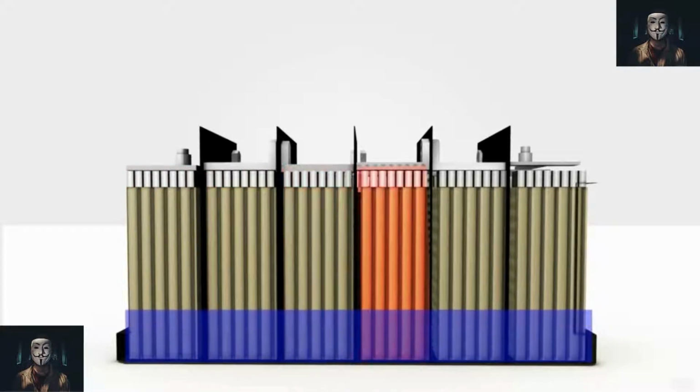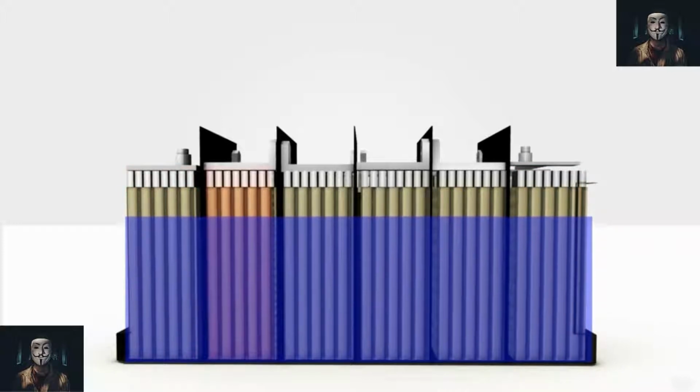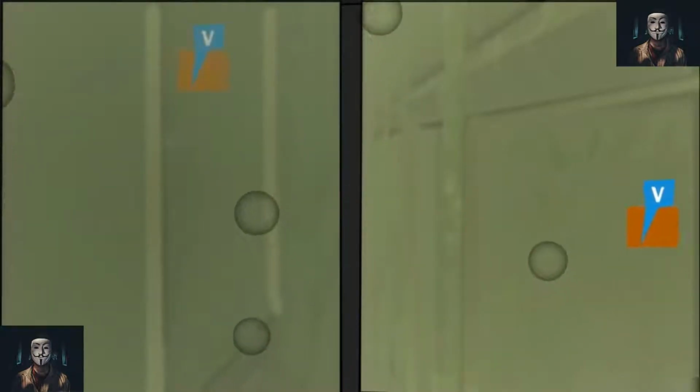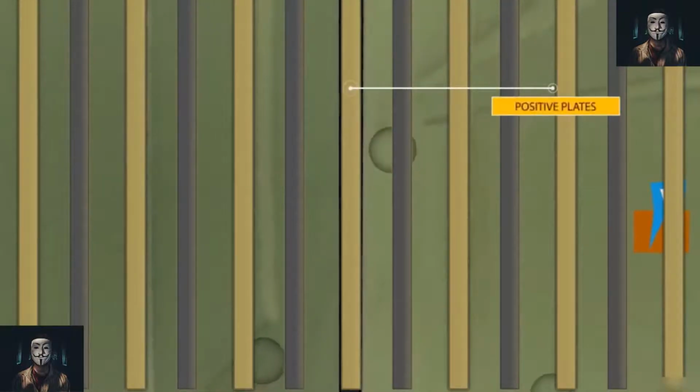A vehicle 12-volt battery is made up from 6 cells. Each lead-acid cell has a nominal voltage of 2.1 volt, which gives a value of 12.6 volt for a fully charged battery under a no-load condition. The 6 cells are connected in series internally in the battery with lead bars. The cells are formed in the battery case and are completely separate from each other.